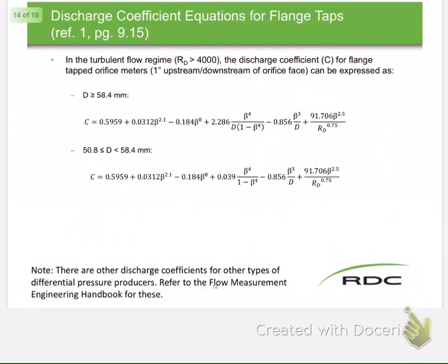So some equations that maybe are not familiar, but they're big, and you maybe recognize them slightly because we've used them in process measurements 3 as well, are the ones for our discharge coefficient here. And you can see that they're dependent on beta, and that's why it makes it an iterative solution where you have to keep going in a circle until it stops changing.